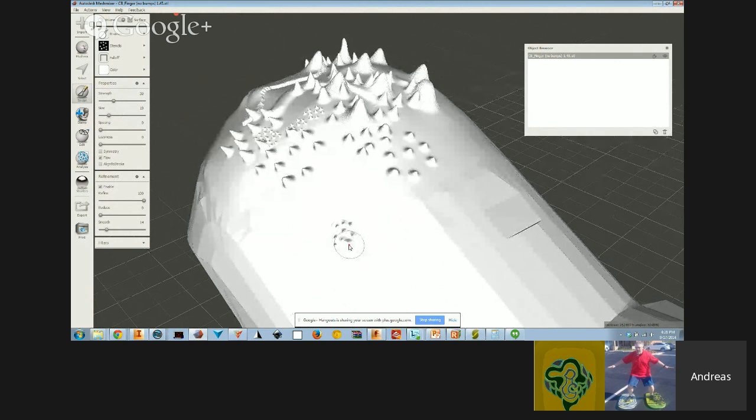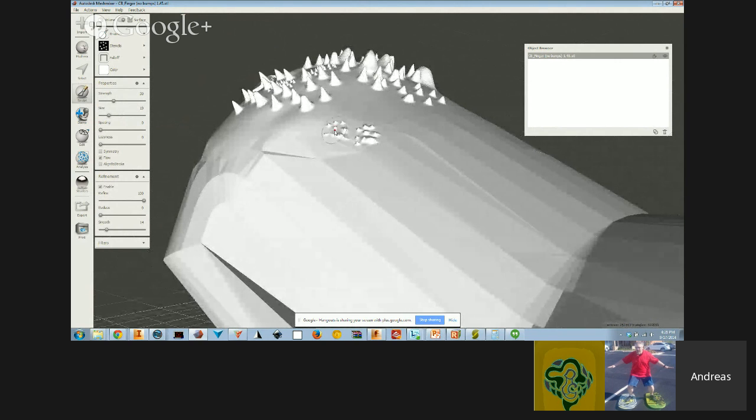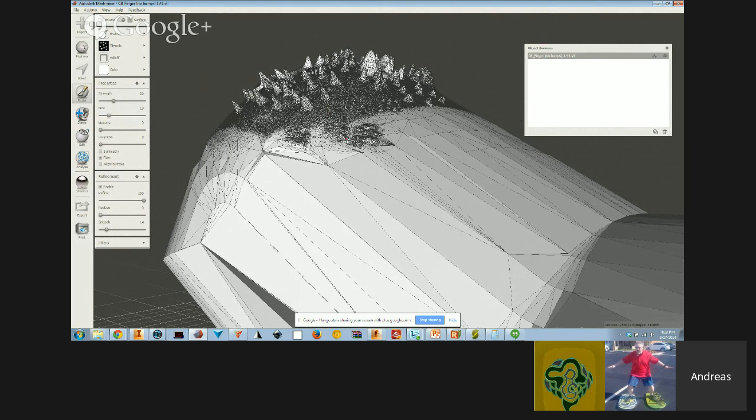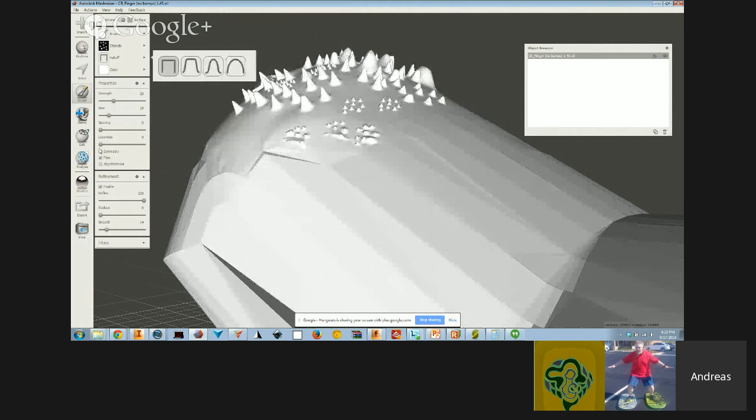In that case, it doesn't look too bad right there. I just find that it can hinder performance, but in this case, it's not too bad. So I used the refine brush to add all these triangles, but you can actually just enable this refinement down here in the parameters, bump up the refinement, reduce down the reduce, and add that stuff on the fly.